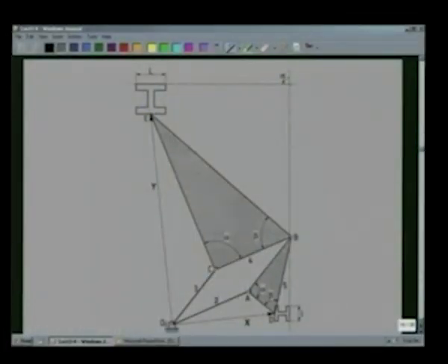This diagram shows the kinematic diagram of the model of the mechanism which we have just now seen, that is that copying mechanism or plagiograph. As we see in this mechanism, we have 5 links. One is the fixed link, O2A is the second link, O2C is the third link, BC is the fourth link, and AB is the fifth link. So, it is a 5-link mechanism. So, let us say N is equal to 5.